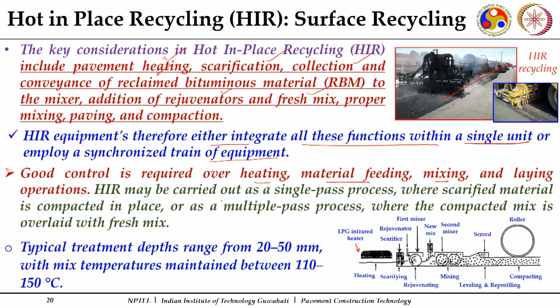Hot in place recycling may be carried out as a single pass process, in which case you produce the recycled mix, where the scarified material is compacted in place, or as a multiple pass process, where over this you can put a new fresh mix also, and then it is compacted. So there may be a recycled mix layer followed by a layer of fresh mix, and they may be compacted together or individually.